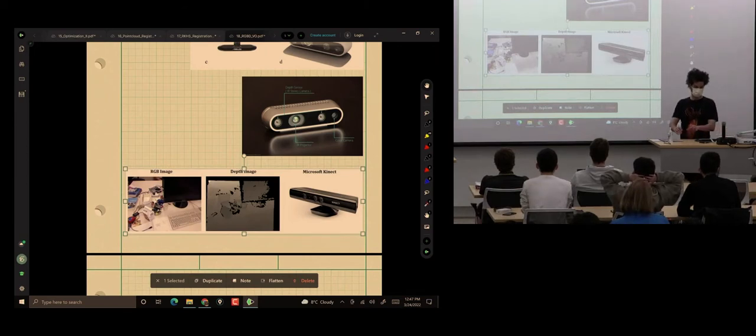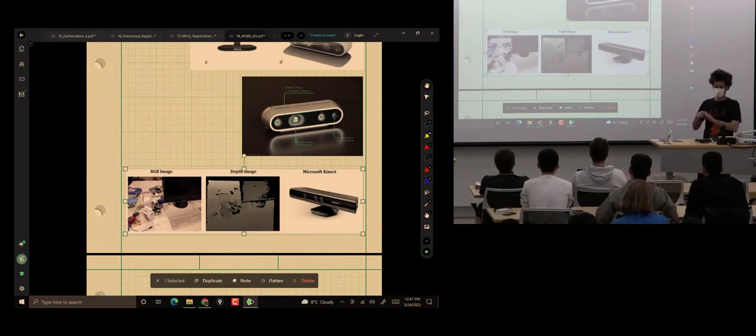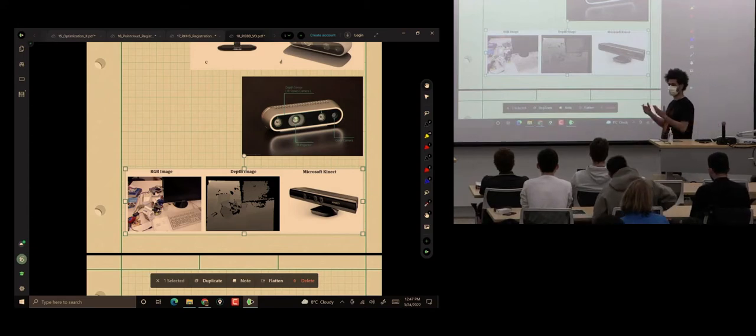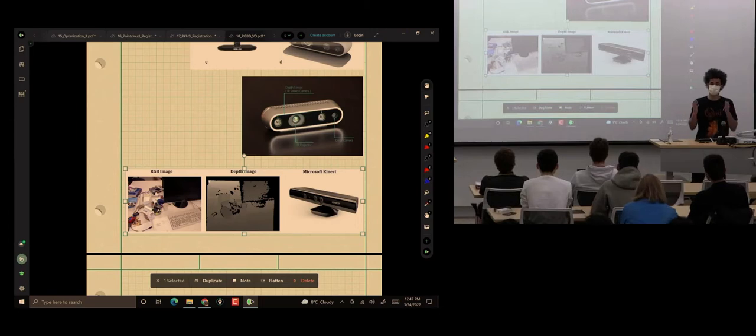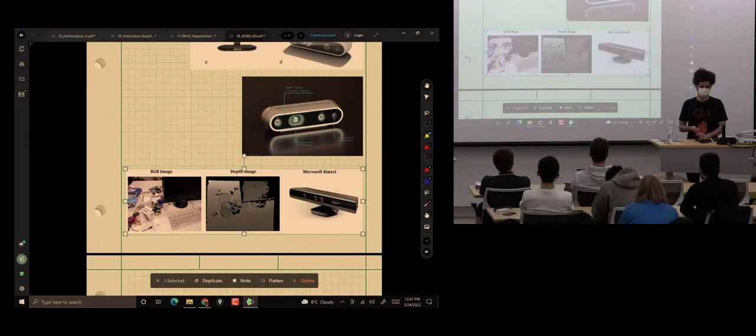So the camera, our algorithms are somewhat agnostic of what brand of sensor you will buy. We're going to assume the data is processed. We have synced RGB and depth images, plus we know the intrinsic calibration of the camera so that we can project 3D points on the image using the projection model of the camera.